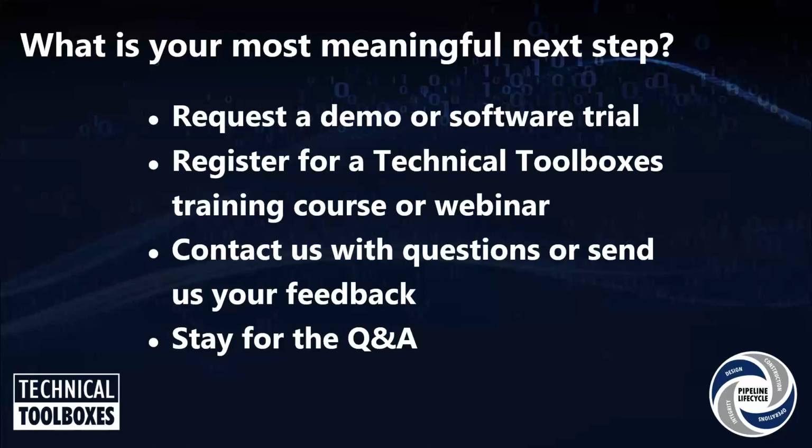The other thing you need to consider is the above ground. What are you going to put for soil resistivity? Well, if you're going to use the soil resistivity of air, it'll give you higher voltage, similar to what you would experience on a capacitive calculation.